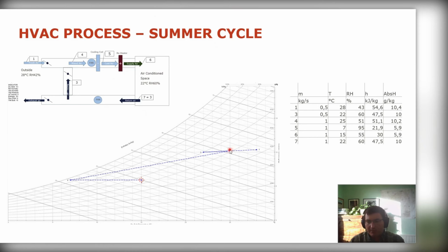Now, generally speaking, what would happen is that you would have to be cooling like that directly, because until you get to the dew point, there will be no condensation coming out. So it all would be sensible cooling for a while until you get to the dew point, and then you can't just continue sensibly cooling because that's an impossibility. So instead, you would follow this curve down towards wherever you want to get to. And you would have both. You would have some reduction in temperature, and also you'll be squeezing moisture out of the air. Your absolute humidity will be reducing, and your relative humidity would remain on the 100% line.